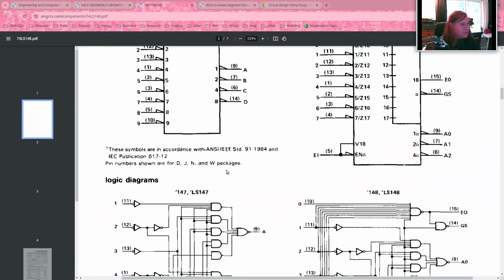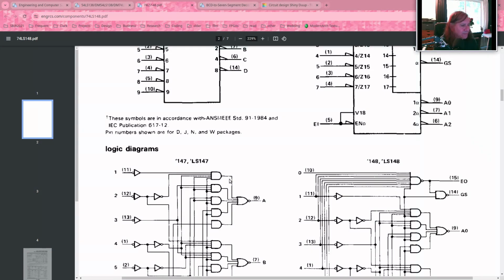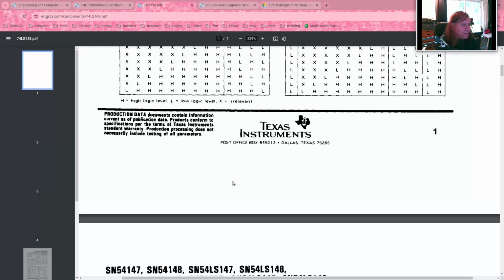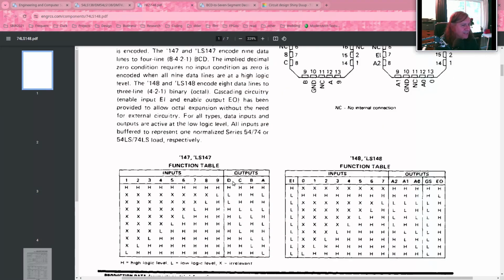Alright, so this is a useful circuit for taking in a series of inputs that might correspond to events that you want to pay attention to inside a computer, and maybe input 9 says the power has failed, and input 8 says some calculation we were performing that's taking time, like a long multiplication, has just completed. And input 7 says a piece of information just arrived on the network interface. And input 1 might say the user has just pressed a key on the keyboard, right?